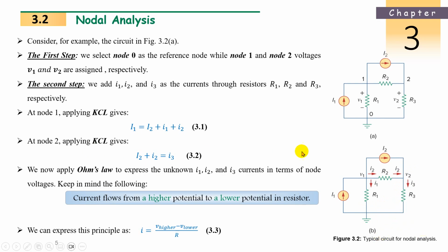No problem. So like this we have to arrange. Now, for this R2, what is the higher potential? Because current is from left to right, we assume left to right. So when current is moving through the resistor from left to right, V1 will be the higher potential and V2 will be the lower potential. So V1 minus V2 will come. If the current direction is opposite, reverse, then V2 minus V1 we have to write.